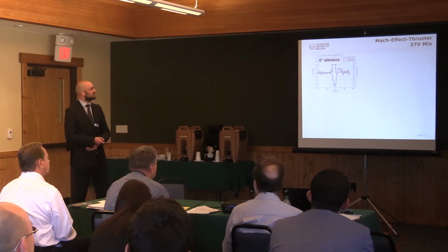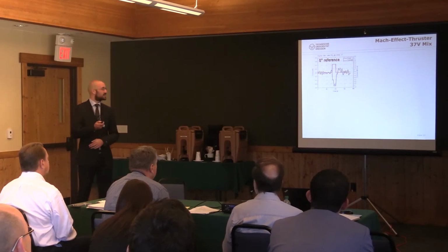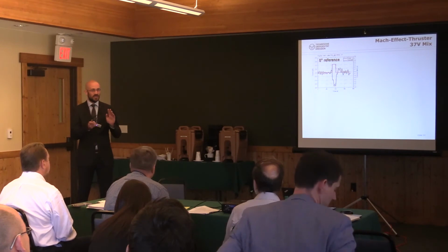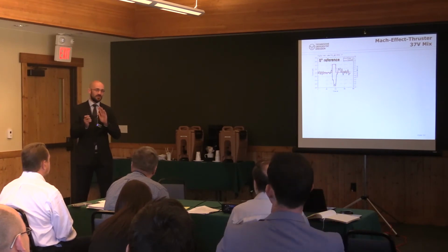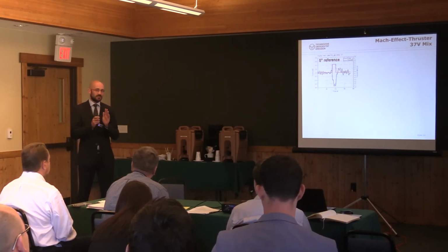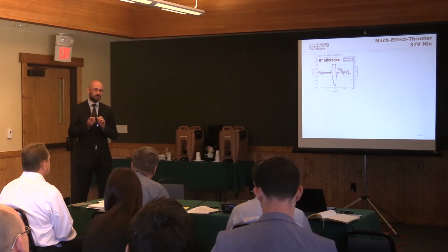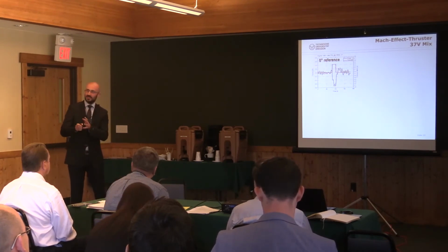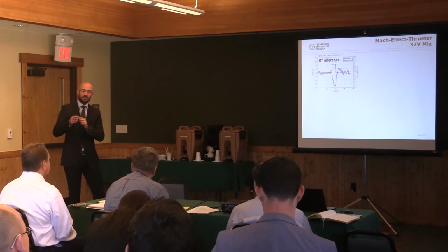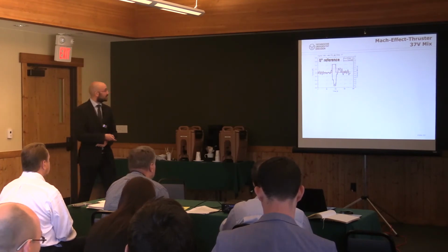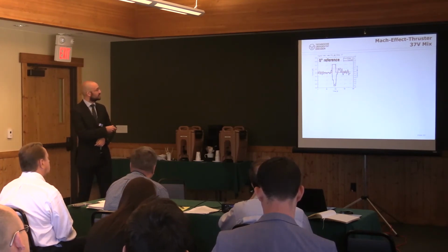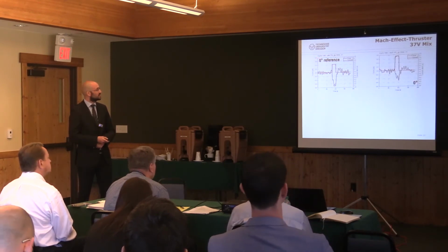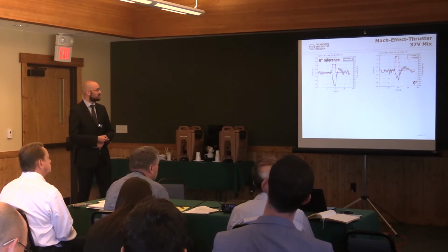Then we did a mixed signal, like Maxime said. If you don't drive it with a pure sine, but with a combination of two frequencies in a sine, you should get a much higher force response because you can use the second harmonic, the piezo effect there. So this is again the reference, the amplitude is again 800 nanonewtons. At 0 degree, it looks in the same direction, but it's not increased, so bad.